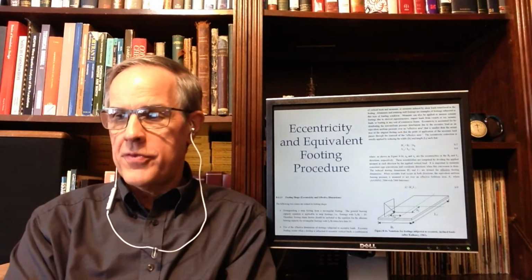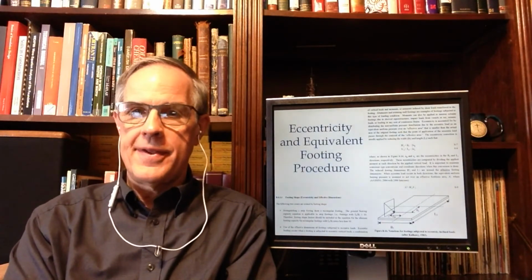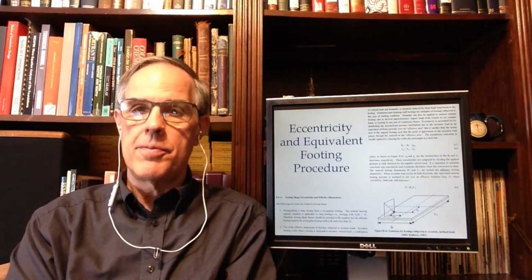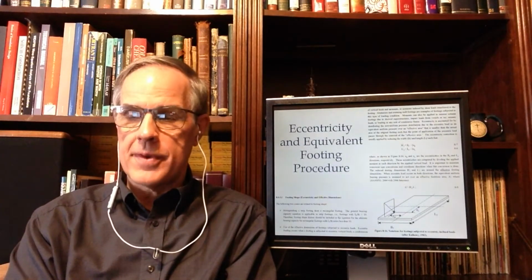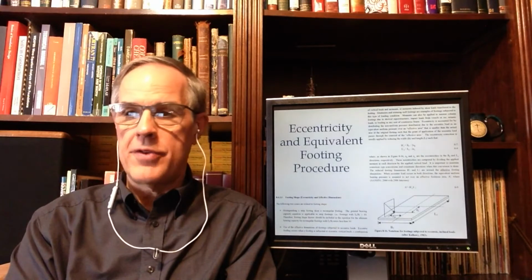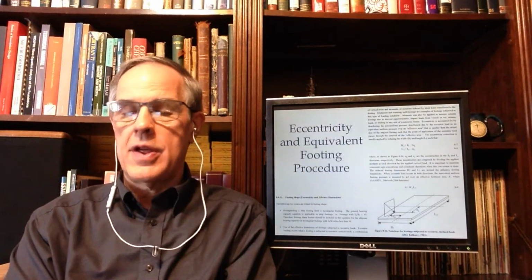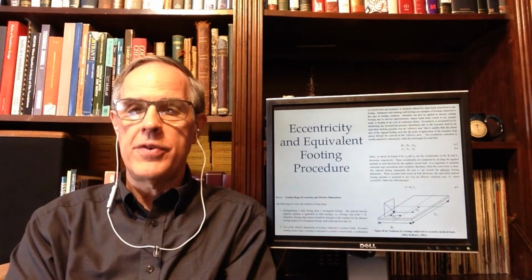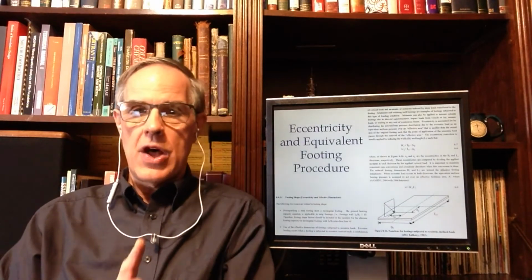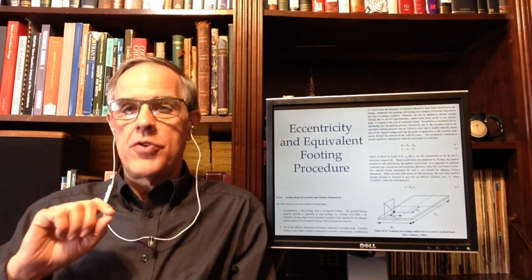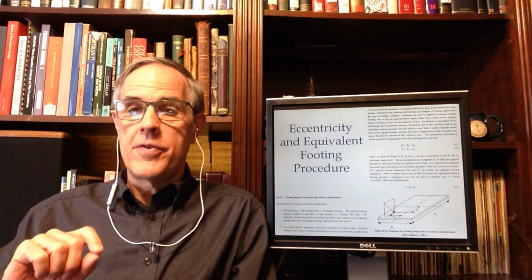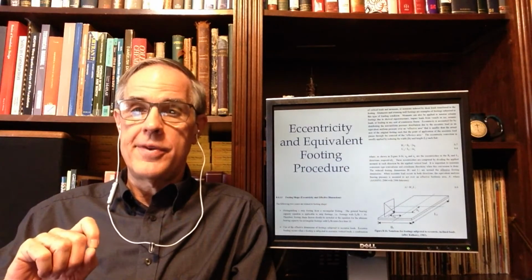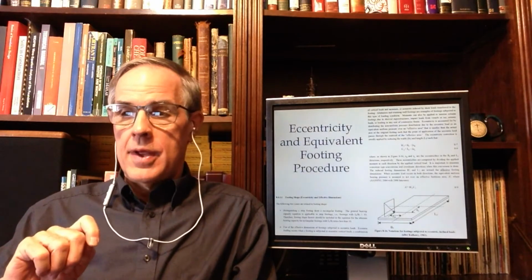The equivalent footing procedure is just described in your book. It's really very simple, but it complicates. You start out once you've determined the load and you determine the eccentricity or eccentricities, and you have to be very careful when you do that and make sure that your eccentricities are in the right direction.